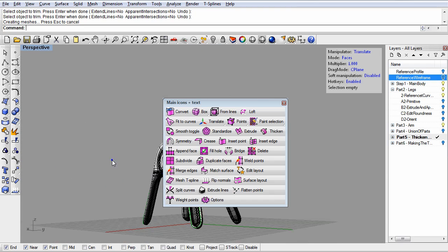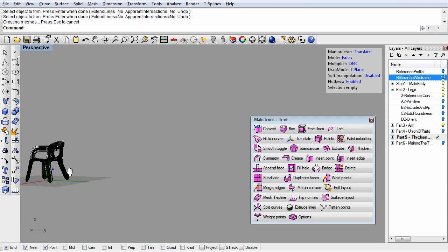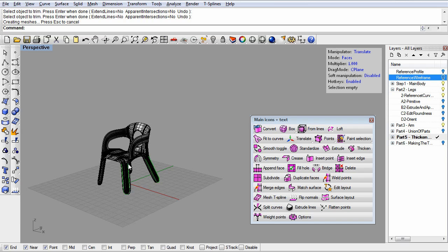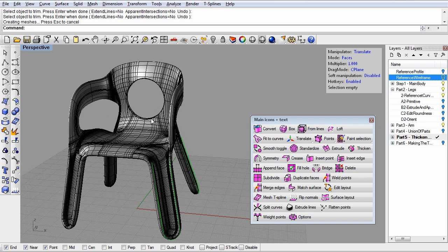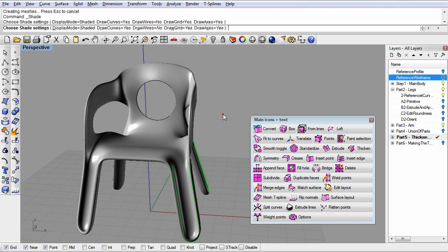And then after the trim you have a polysurface with that exact hole in it. So that's kind of the way to get exactness out of your T-spline. And again, this is the same shape that we had modeled, only now it's converted to NURBS. So as far as a workflow goes, you'll want to stay in T-splines as long as you can and then convert to NURBS at the end to do the trimming.